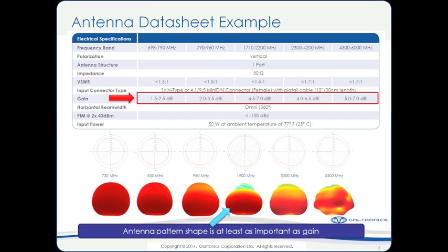Yeah, so we made the comment earlier that our antenna patterns are directed towards below the ceiling, and we're actually relying on that bounce off of the concrete floor or whatever structure is below. The presence of multipath is required to be able to separate those two transmitted signals in a 2x2 MIMO system.